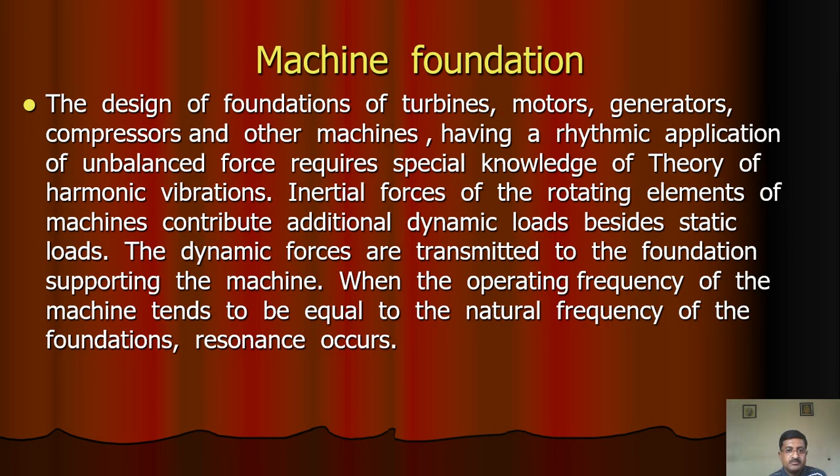Inertial forces of rotating elements of machines contribute additional dynamic loads besides static loads. The dynamic forces are transmitted to the foundation supporting the machine when the operating frequency of the machine tends to be equal to the natural frequency of the foundation,